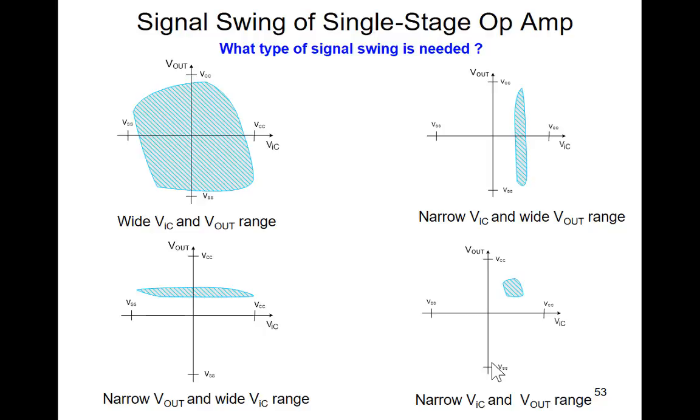How about this circuit? What's the common mode input range now? Still zero? Common mode input is VN. If VN was a big signal, this circuit requires a large common mode input range. Would an op amp that had this characteristic be suitable for this application? No. We need something like this. Or in this case, we might need something like this.